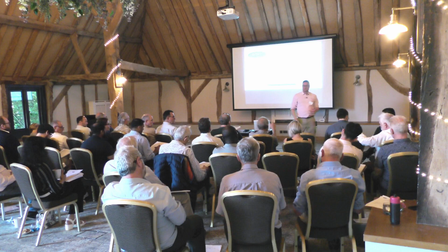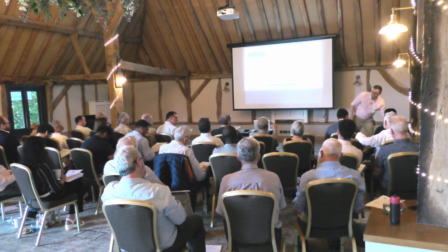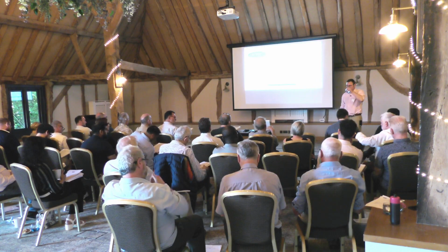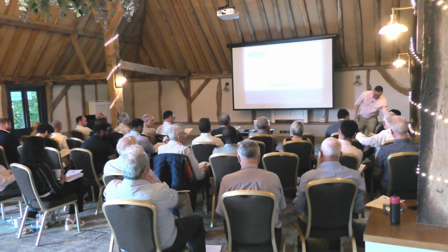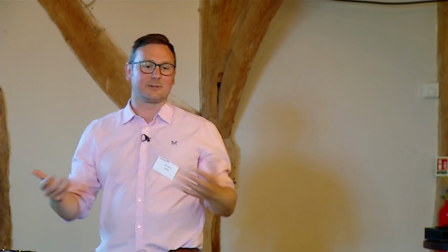Sorry, the 200 metres squared, you do a lot of measurements where they're over a certain height in the roof conversion itself. 200, are we talking about floor area? So the 200 metres squared relates to designation of that building as a large dwelling house, and that's floor area, so whatever the height is irrelevant. Exactly that, for that purpose. Obviously, floor height does have massive implications elsewhere, but bearing in mind that I'm trying to focus on dwelling houses, realistically we're going to be focused on 2- and 3-storey dwellings.